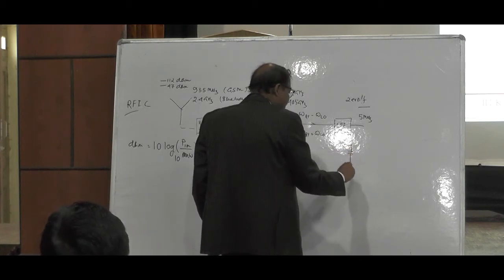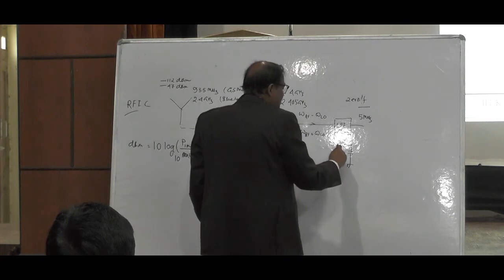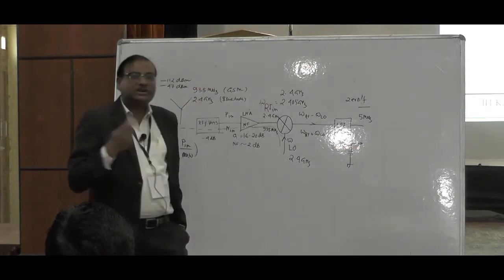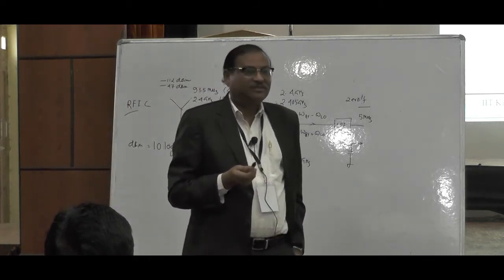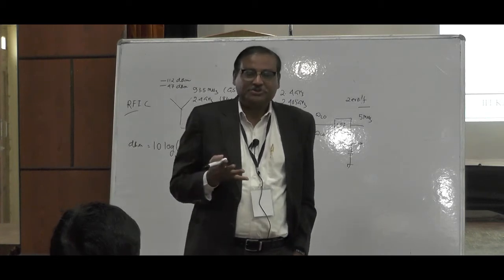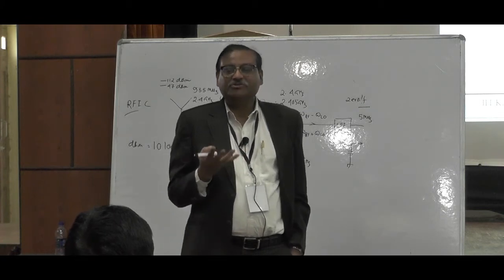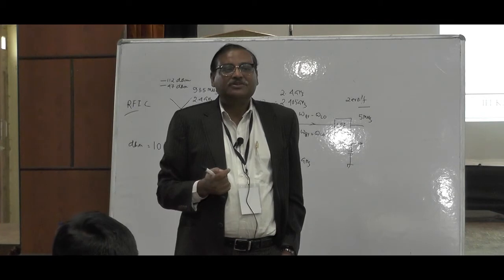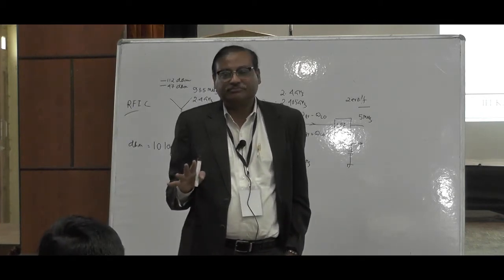When the DC voltage tries to charge my capacitor, the capacitance immediately gets charged because of the DC offset. Then the capacitance will certainly have more voltage. In spite of the desired signal, we will end up with a huge DC voltage. It will saturate the rest of your signal, so you will never be able to extract any signal.